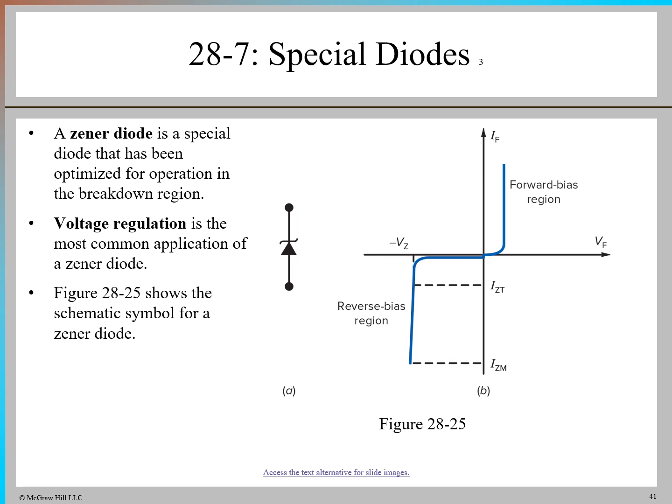When reverse biased, the Zener voltage stays nearly constant once the breakdown voltage is reached, and small variations occur due to Zener impedance. Zener diodes are rated by their breakdown voltage and power dissipation, and their power is calculated by multiplying the Zener voltage by the current. For example, a 12-volt Zener diode with a 30 milliamp current would dissipate 360 milliwatts.